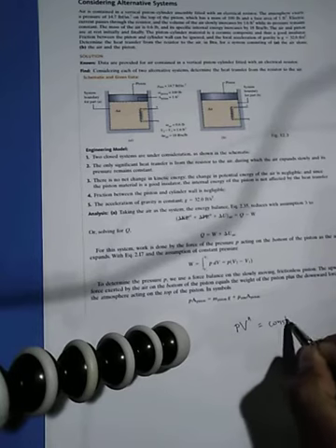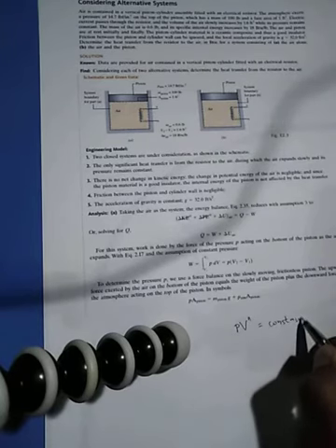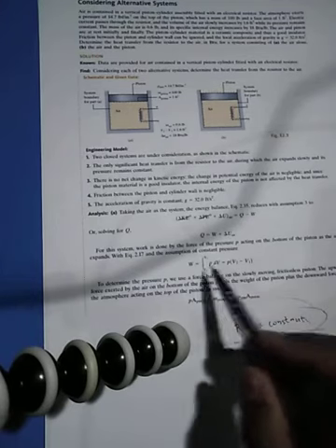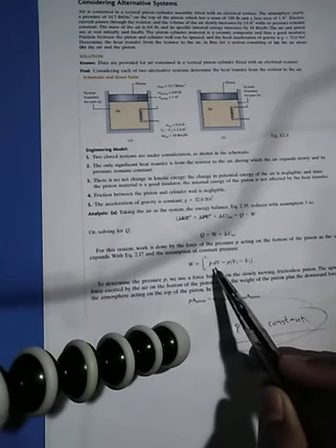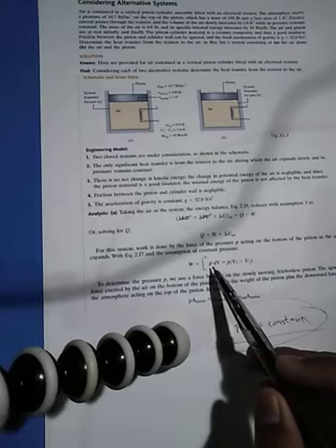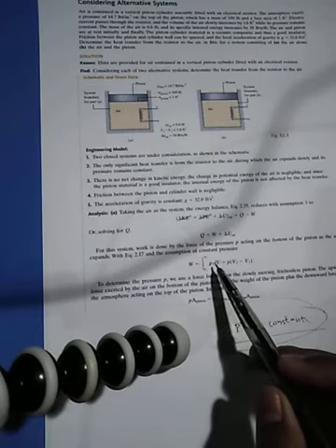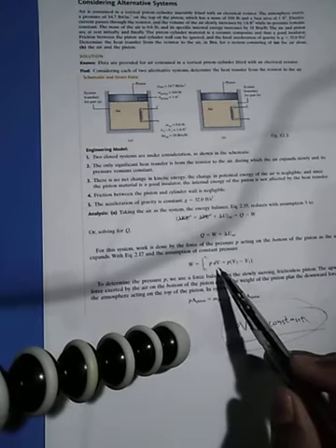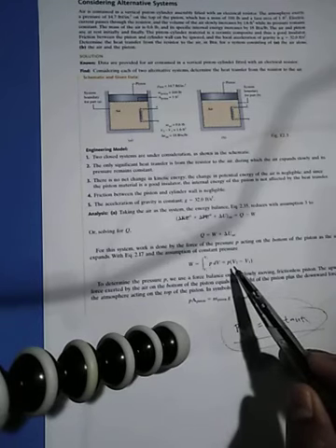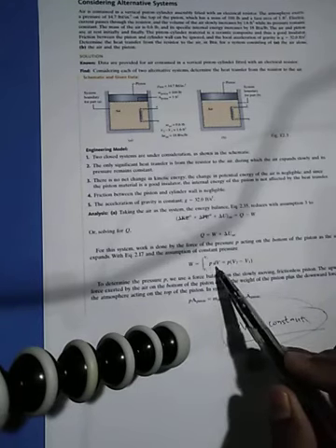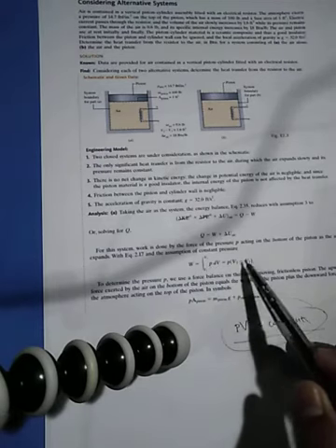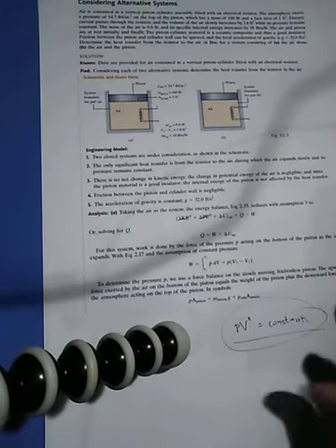This is for polytropic process, no. So hindi na natin to siya kakailanganin just because we already assume here that the friction between the piston and cylinder wall is negligible. It means that the pressure is constant. Okay, so in this case, since pressure is constant, we can already integrate this dV here. Since constant naman yung P natin, we can just say that P multiplied by V2 minus V1. Okay, so yun yung ibig sabihin nun.